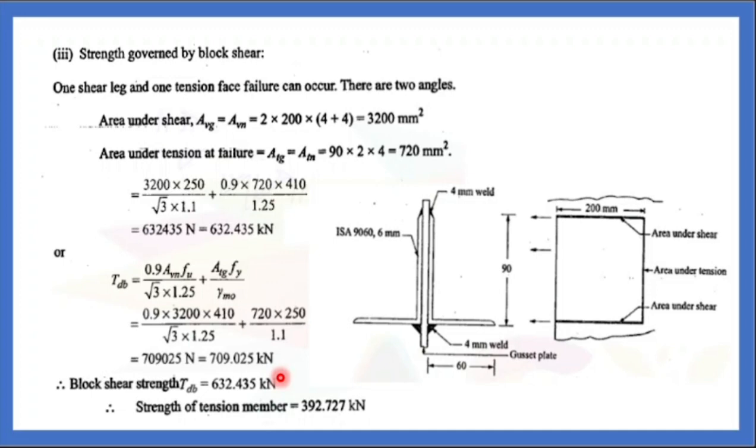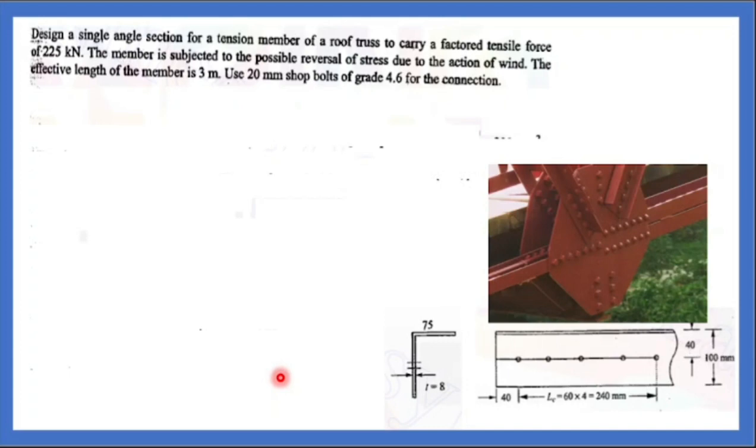Check the previous problem. What have they given? They have given a plate 130 mm width and what is the thickness? 12 mm. They are given a thickness and they will ask how much is the load carrying capacity for this section. The second way of asking a question is, I need to carry a member of 700 kilonewton. The load is 700. Design the member. For the 700 load carrying capacity, you design the member. You have to say the sections. This is the reverse type of problem.